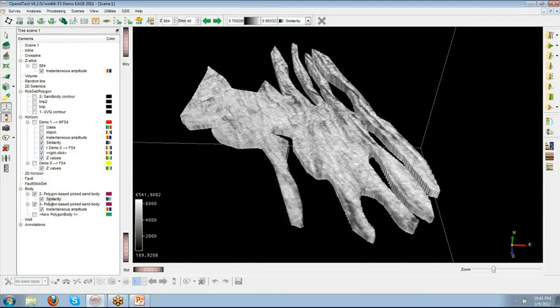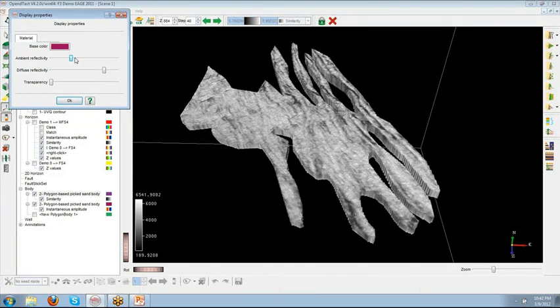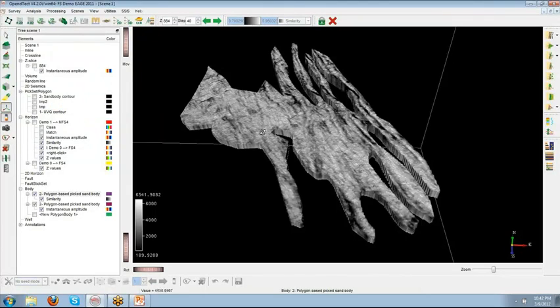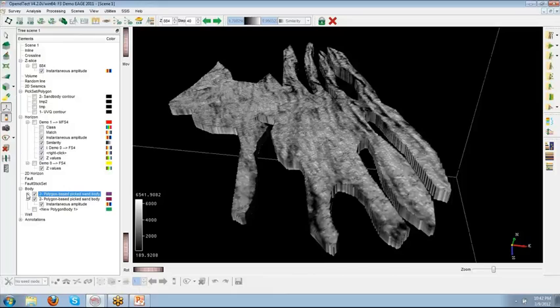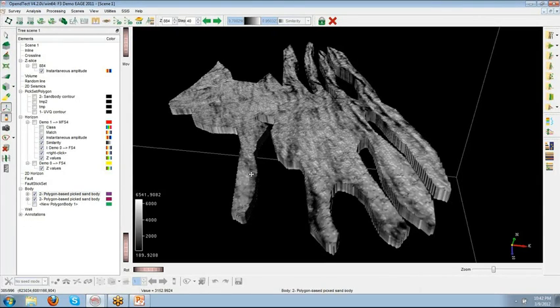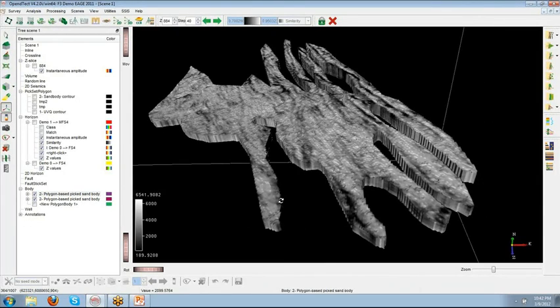I need to apply the relevant color bar and set the properties of the geobody, because that influences the look and feel of the attribute. And if you want to toggle very easily between the two attributes, so the two geobodies, let me remind you, you have this option in the graphics toolbar that allows you to display the current element only.